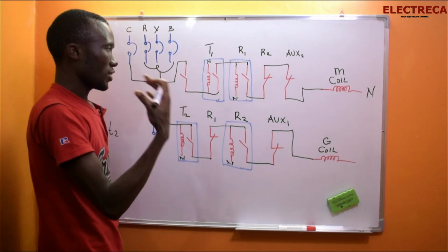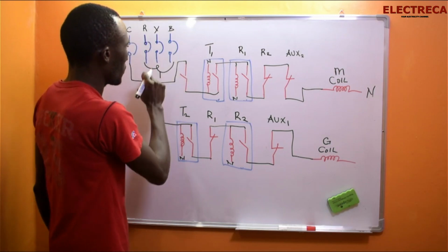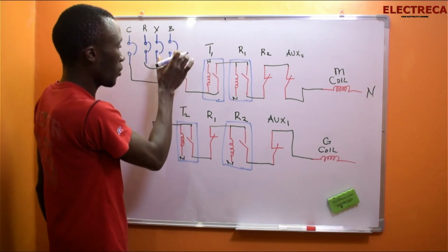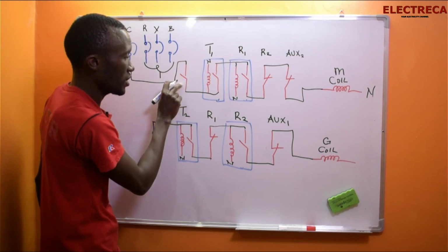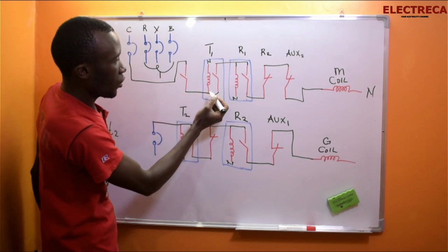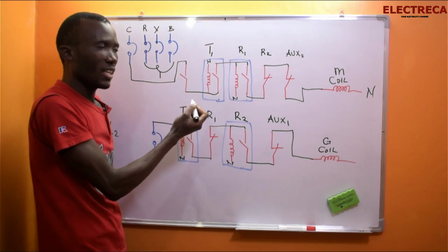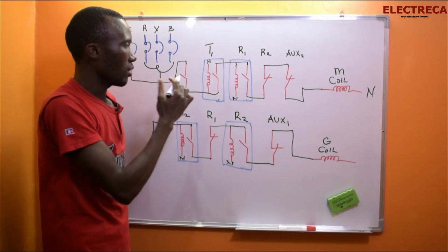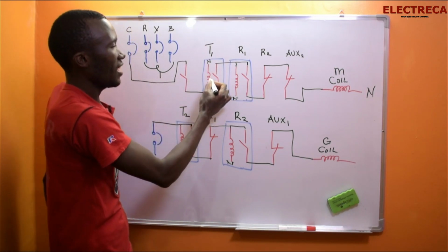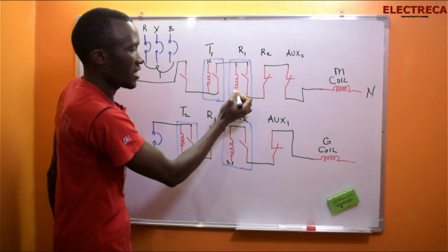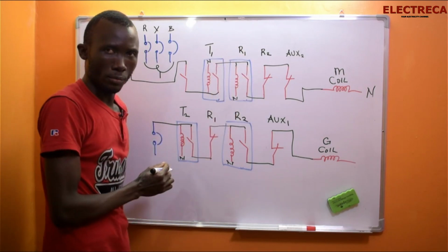Now, under normal circumstances, the power supply, of course, you supply the coil of the relay, it will get energized, we close this one, and it energizes the timer. The timer closes its normally open, and then current goes through it, it supplies relay number 1, okay?